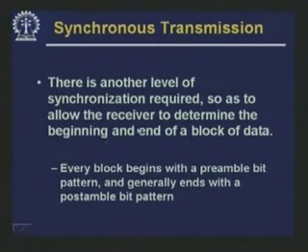So, for synchronization we require this. We need to say that this is where the data begins and this is where the data ends. Every block begins with a preamble bit pattern and generally ends with a postamble bit pattern. That means each block starts with a preamble bit pattern, that is the start of the block, and then the block goes, and then there will be some part at the end which is the postamble.